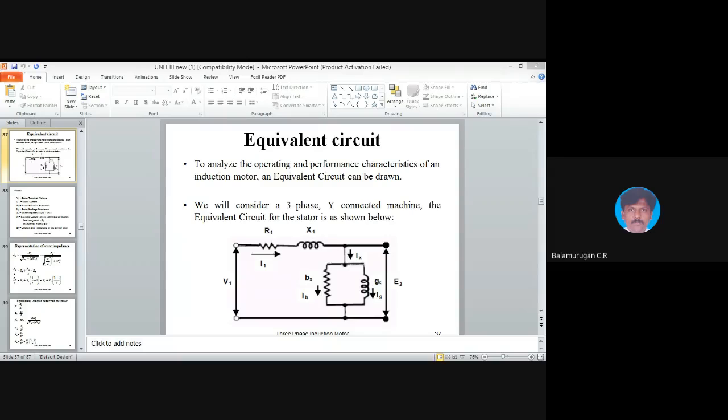We discussed the RMF, that is, the rotating magnetic field. We discussed the phasor diagram for different angles. The rotating magnetic field will be generated at the stator side, and it will have a speed near the synchronous speed. For that, how the rotating magnetic field is developed and what the magnitude of the flux is, we derived with the help of the phasor diagram.